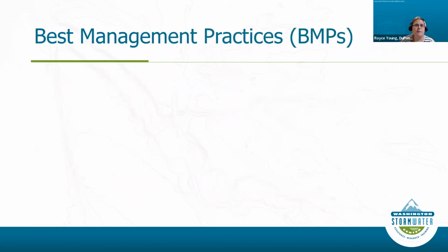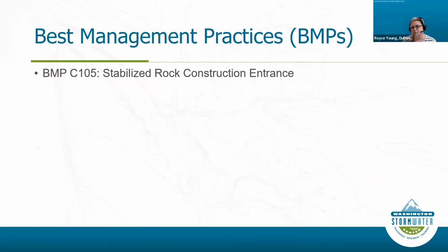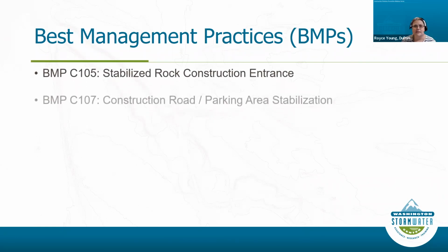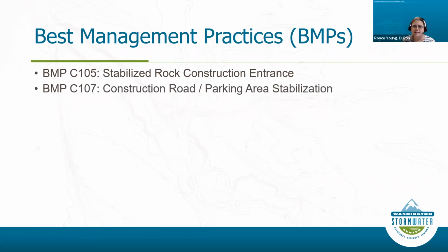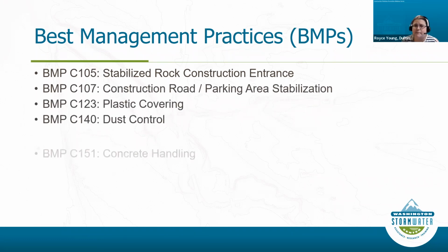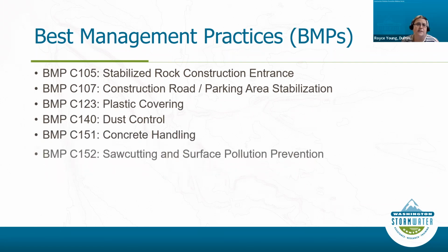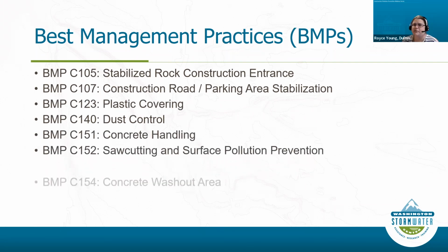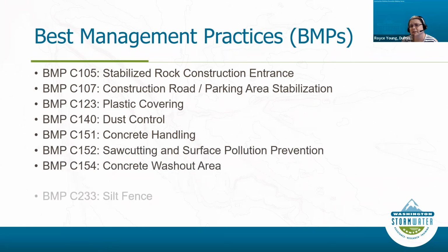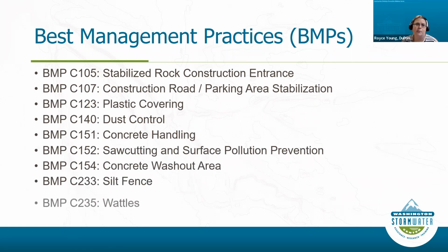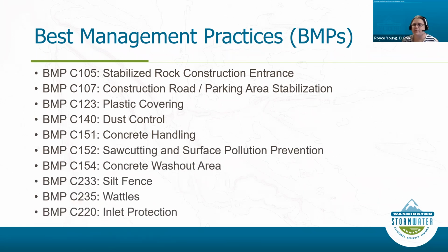So, best management practices. Now that we've thought about all the activities that can create pollutants and what those pollutants are, let's look at some of those that could be listed. Stabilized rock construction entrance, construction road or parking area stabilization, plastic covering, dust control, concrete handling, saw cutting and surface pollution prevention, concrete washout area, silt fence, wattles, inlet protection.